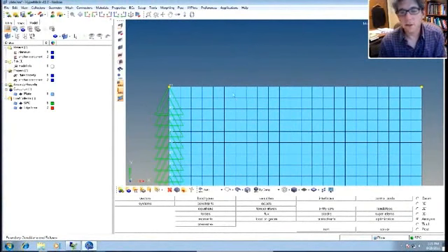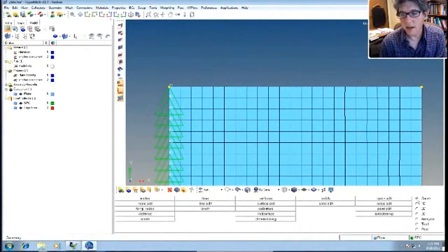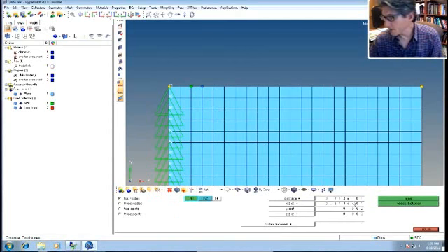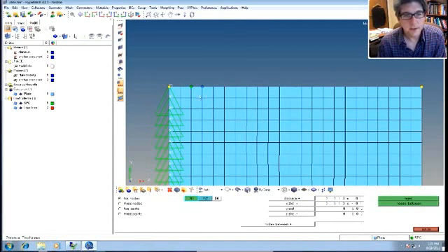I'm going to do that by, all these elements have the same size, so it makes my life a little easier. Let's figure out how long an edge is. So if we go to geometry and we pick distance, pick 2 points. You can see the distance between those 2 points is 0.39 inches, right? 0.39 length units.